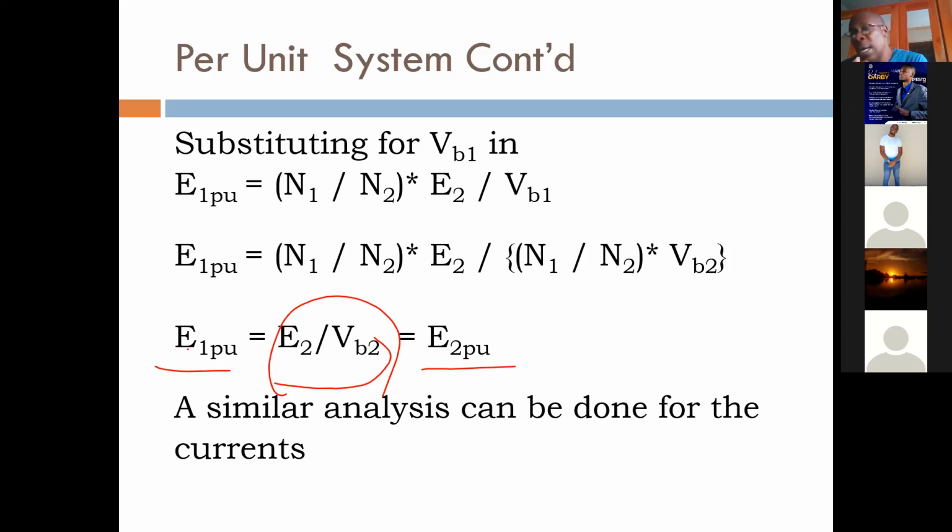So we talk about nameplate rating: what the piece of equipment you're purchasing is rated at. But when you put it in that system, you need to do some calculations. You want to be able to use the system rating to carry out your calculations. And that's what we are going to be looking at. How do I convert from per unit on the equipment rating to system per unit? That's what we're going to talk about right now.